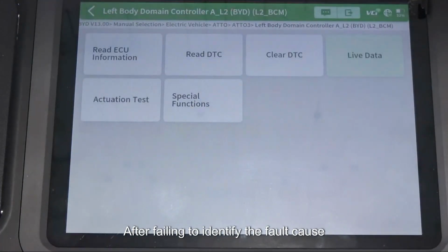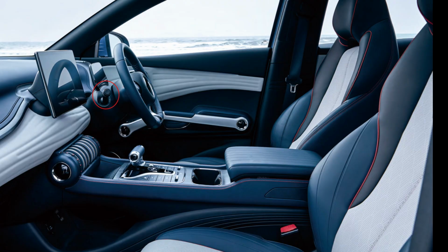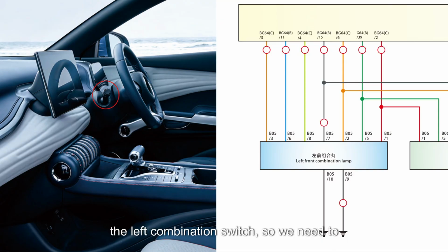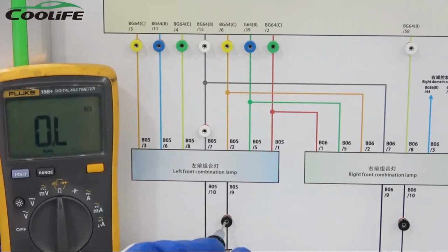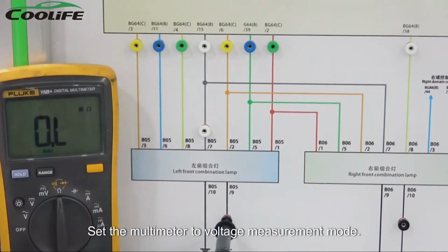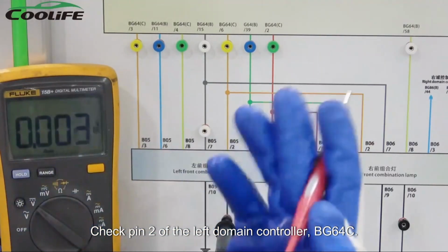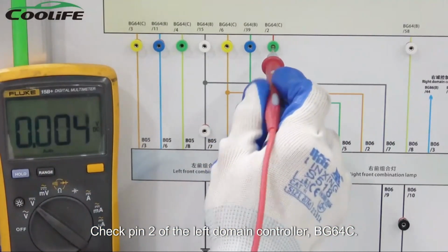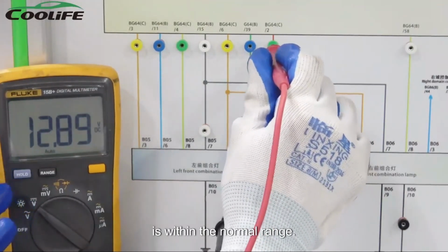After failing to identify the fault cause using the diagnostic scanner, we will use a multimeter to check the relevant circuits. The rear position light is controlled by the left combination switch, so we need to prioritize checking the circuit in this part. Verify the multimeter. Set the multimeter to voltage measurement mode. Check pin 2 of the left domain controller, BG64C. The measured voltage is 12.9 volts, which is within the normal range.